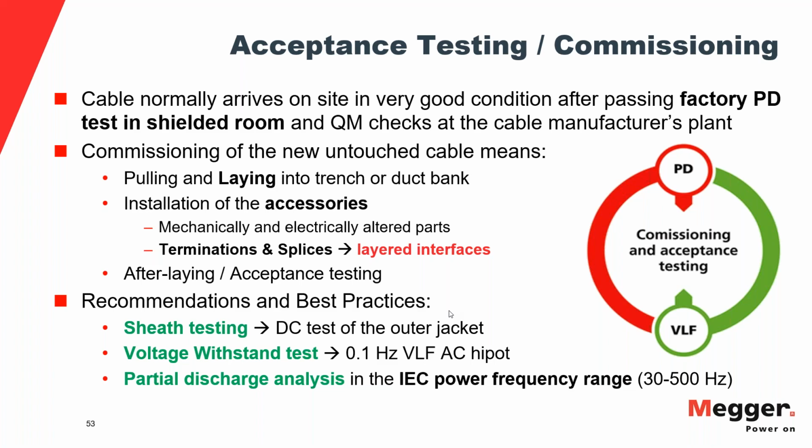The only thing you might be able to see with a tan delta test that is remotely related to a localization would be a wet splice, especially when you listen to Marshall's answer.